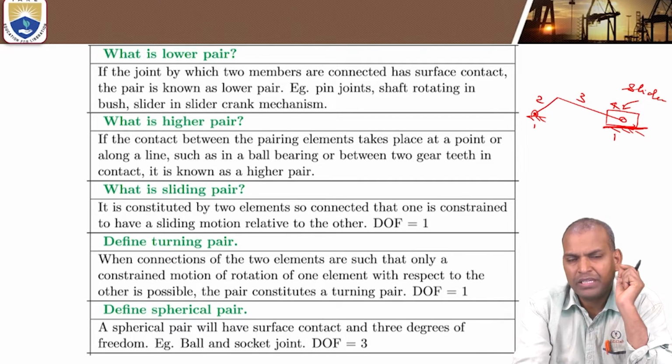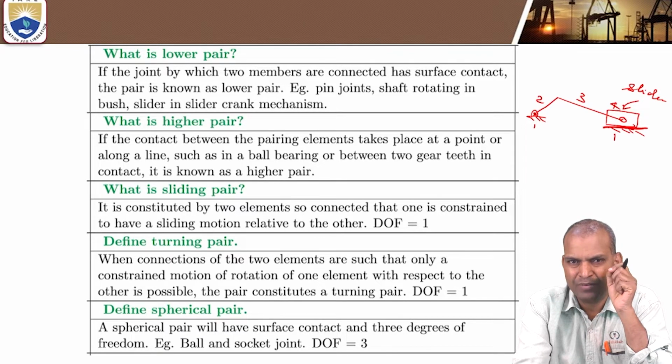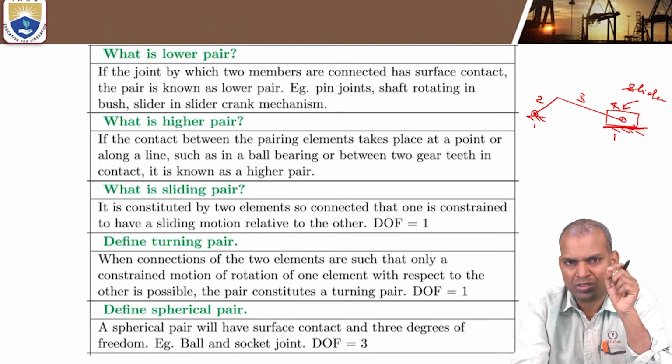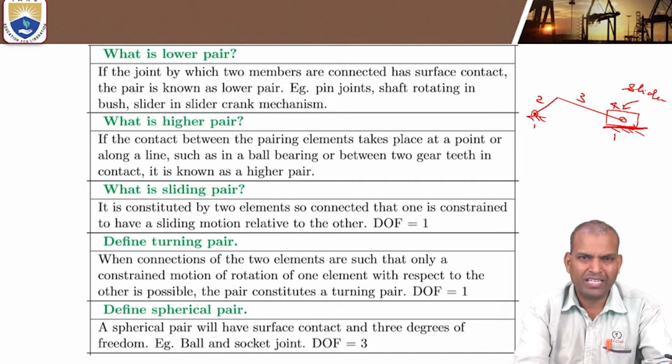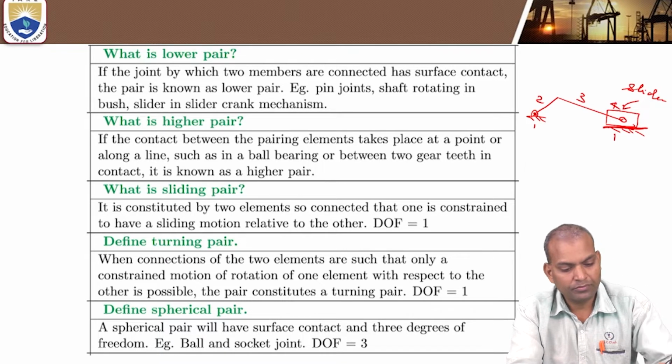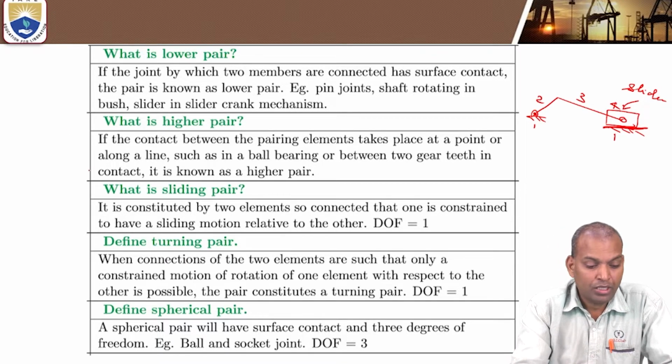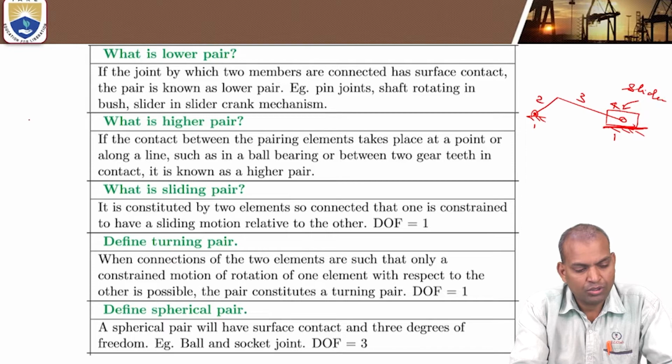Now the contact between cam and follower is a point contact. For certain cams, suppose a knife edge follower having contact with anything, there is a point contact. And a roller follower in contact with a cam is a higher pair, a point contact. And a flat faced follower, when it is in contact with any circular body, also comes under higher pairs. That is the meaning of higher pair. So the examples here mention the contact between two gears. There are teeth here, two teeth.